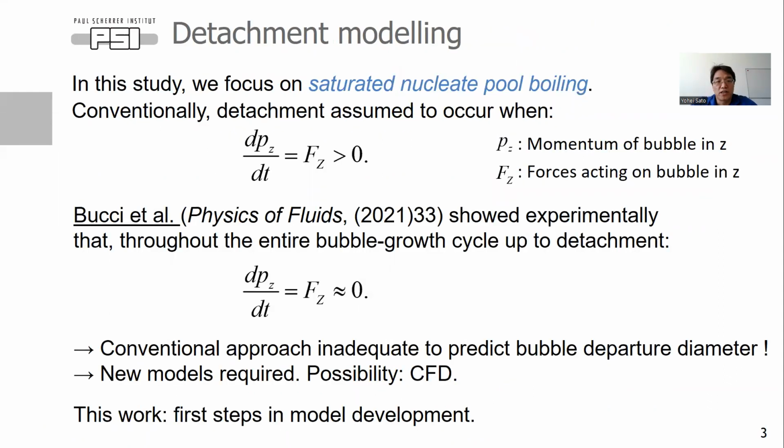And in this study, we focus on saturated nucleate pool boiling. Conventionally, detachment is assumed to occur when Fz, the force acting on the bubble in the z direction, is larger than 0, like this equation. And here, P is the momentum of the bubble in the z direction.